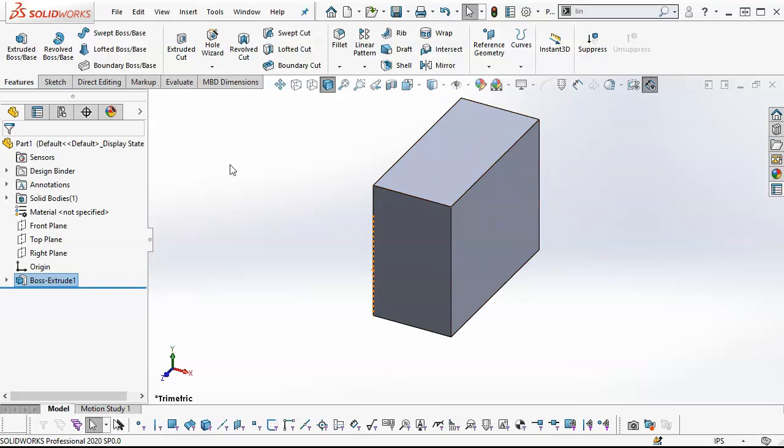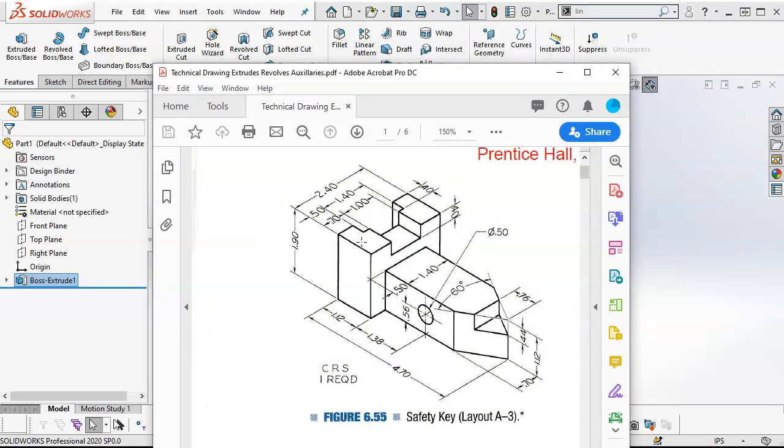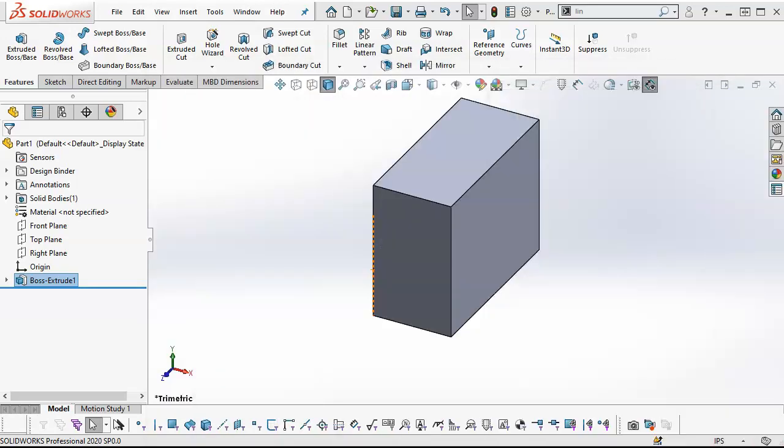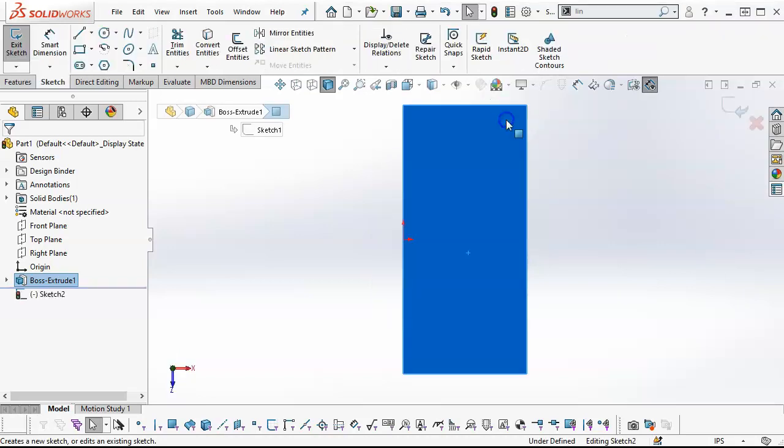Alright, so picking the next face, we have a couple of choices. If I wanted to work from this top face and make this material removal from solely the top, I can do a couple of rectangles, or I can pick from the front face and go that way. That could go from the top face. It also can come from the bottom. So we're making a lot of little decisions as we go, and we design for convenience and we detail for manufacturing. So as I go through the process, we'll stay with some that are easy.